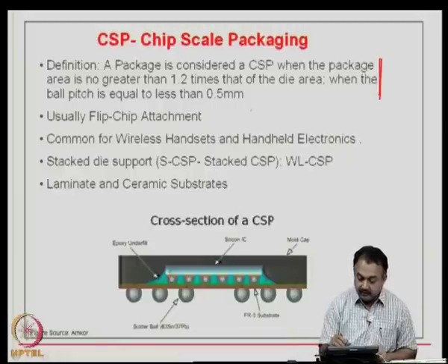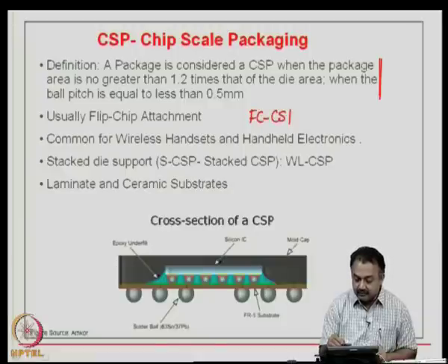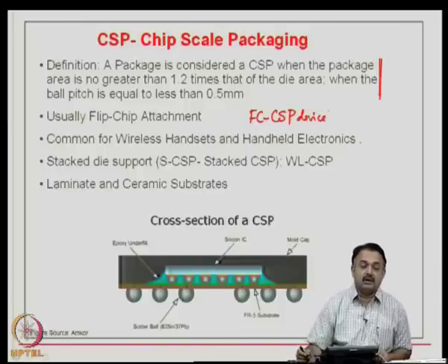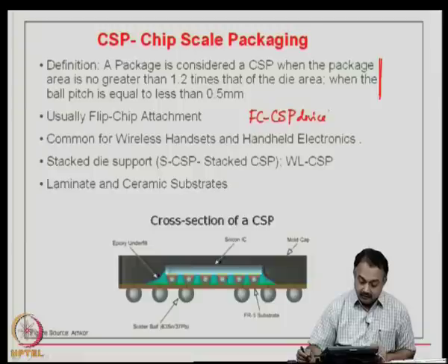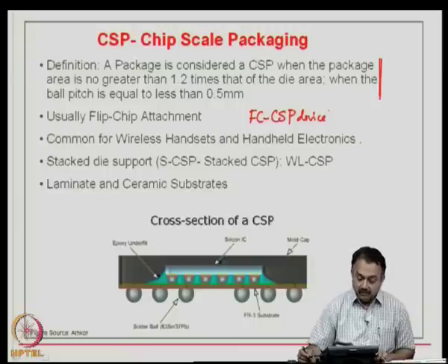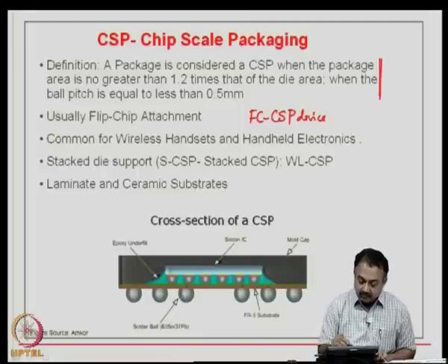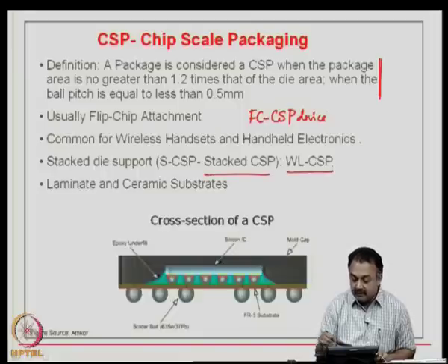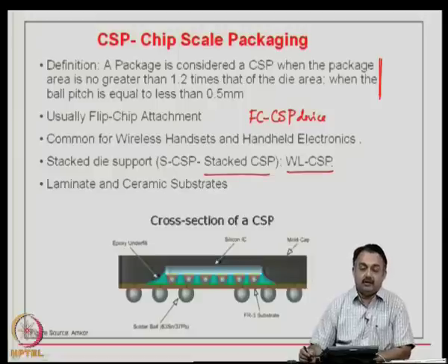In a CSP, normally it is a flip chip attachment. So, you can call it as a flip chip CSP device, because only this kind of a construction will give you a very high pin count. It is very common for handheld applications, wireless handsets and so on. It is possible to have a stacked die support. Therefore, you can call it as a stacked CSP, and if the CSP is manufactured at the wafer level,